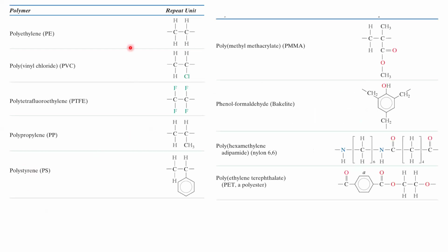Here there are different types of polymers: polyvinyl chloride, polyethylene, polypropylene, polystyrene, where styrene has an aromatic ring, polymethyl methacrylate, and phenol formaldehyde. PET is another polyester, used for biomaterial and packaging applications. Nylon 6 is yet another polymer, with nylon 6,6 having very good thermal resistance. So a wide range of polymers is available, with different types of manufacturing and processing.